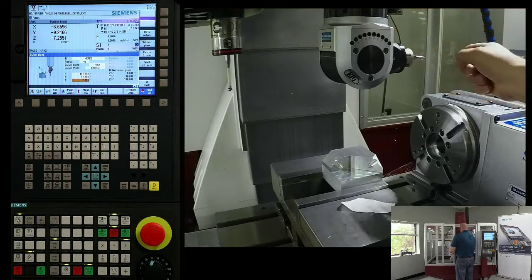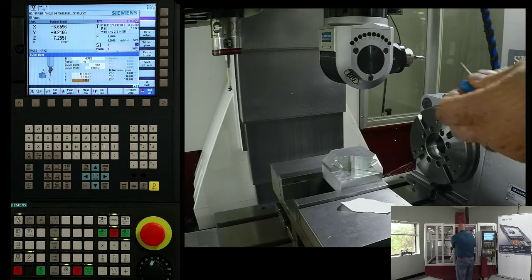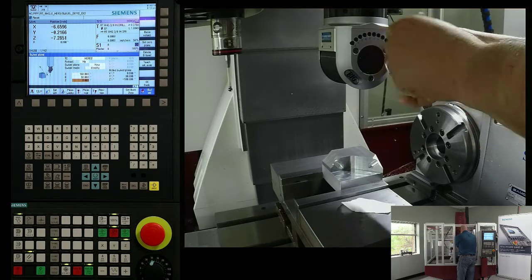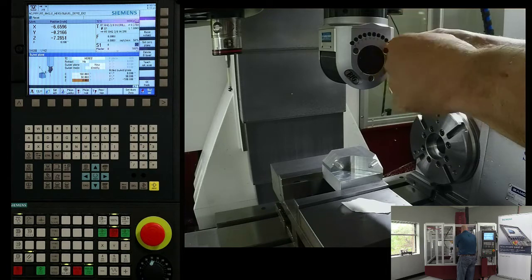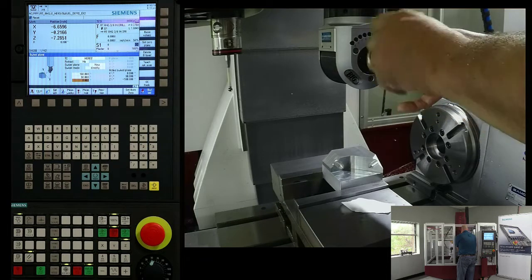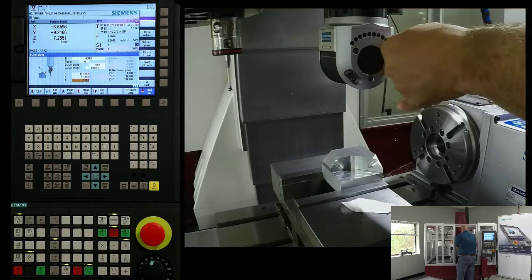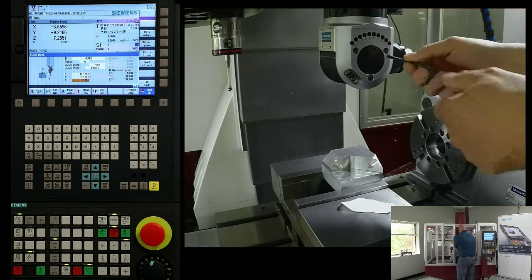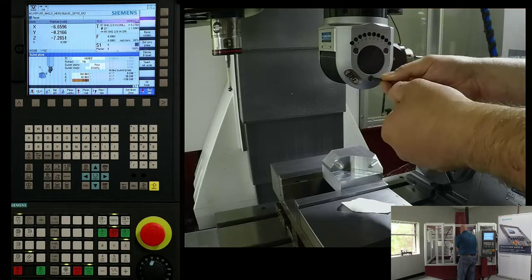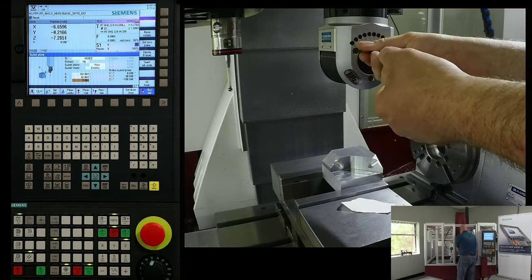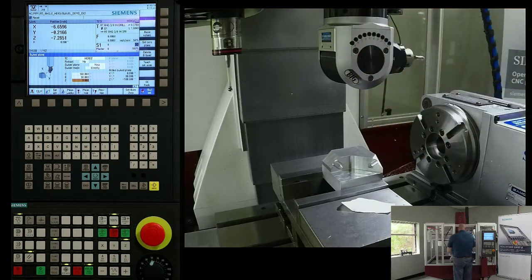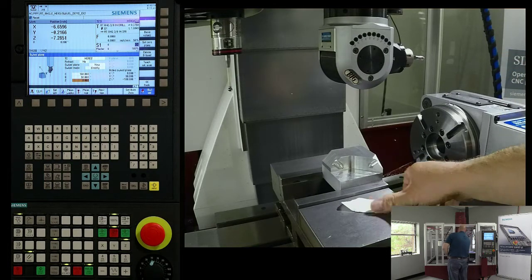And then as I adjust it, I can indicate across and square up the unit. I'm going to go back to 0. Snug it up. You don't have to go tight on this by any means, just until it stops. We'll snug up these bolts just because I'm moving around a little bit, but I'm not going to go crazy. Certainly if I was going to machine, I would tighten that up.